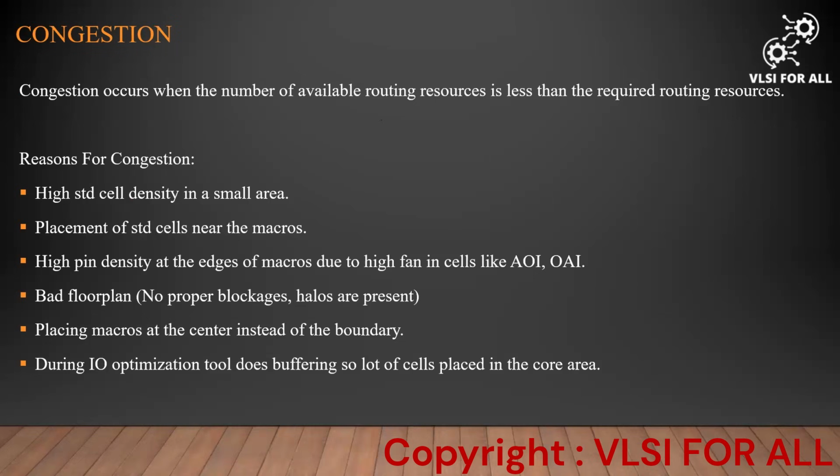Then, how the tool performs: it breaks the entire core area into small cells, which we call G-cells. Whenever it has to connect the standard cells, it will use some routing resources, right?